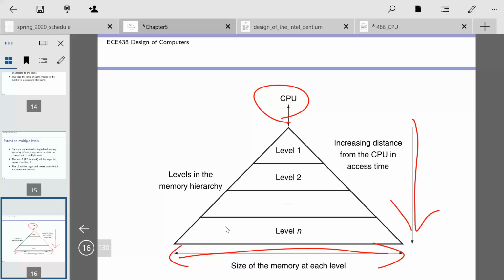Well, the actual die is much smaller than that BGA package. So we can actually fit multiple dies within a package fairly easily. But there's yield problems. It's a tricky manufacturing problem for the folks that package. You can end up having cracked dies and all kinds of weird things like that because you have different thermal coefficients of expansion and all of that. It becomes a material science problem very quickly.